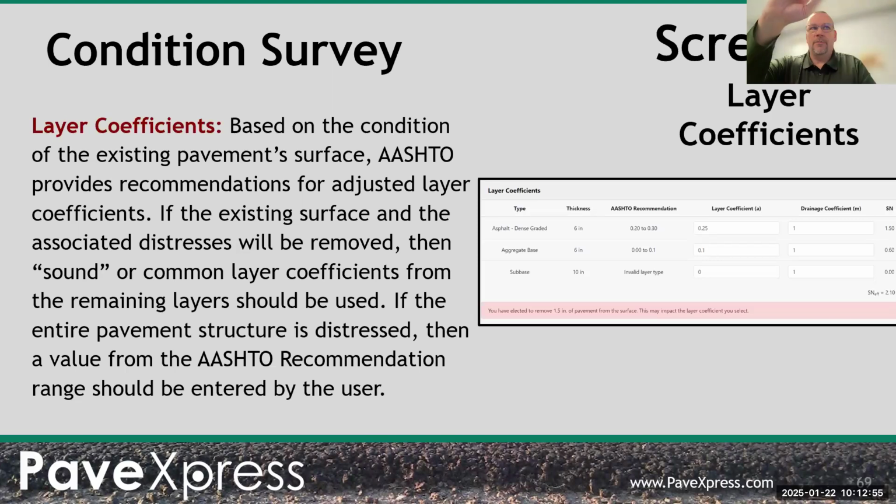So basically, based on your pavement thickness and structure when it was new, it had a structural value of, say, 5. Now, after 20 years, if I've got a lot of degradation, I might be down to a structural number of 2. Based on my 15-year life of this overlay, I've got so much traffic that I have to have this required structural number.